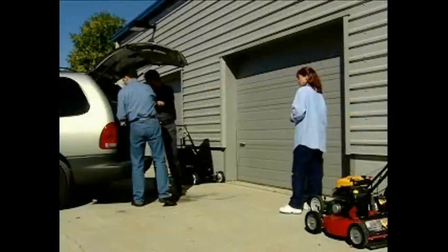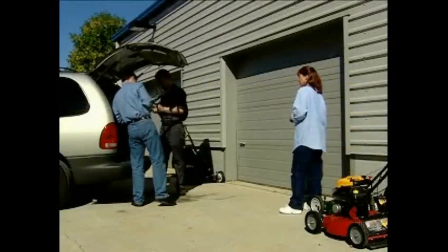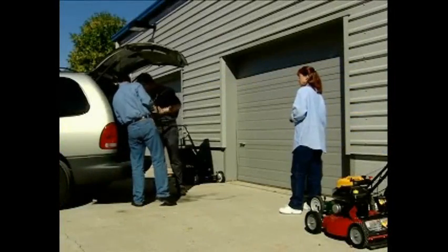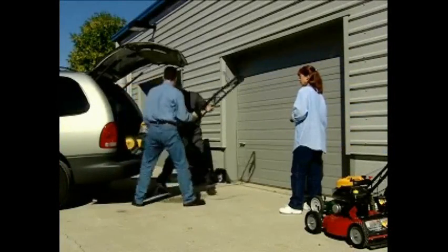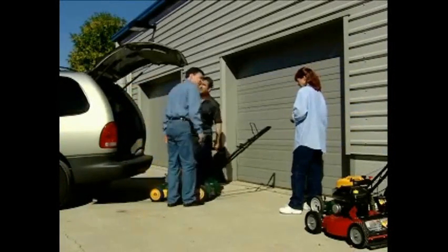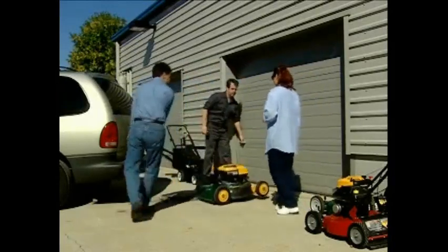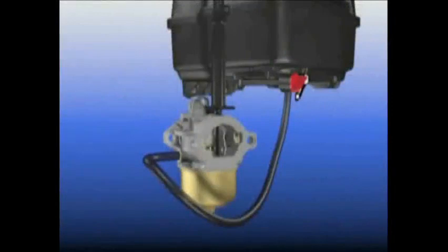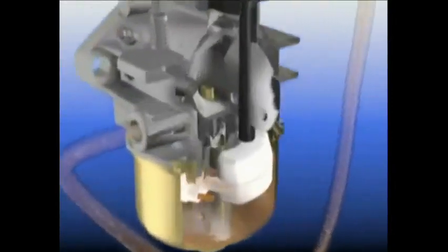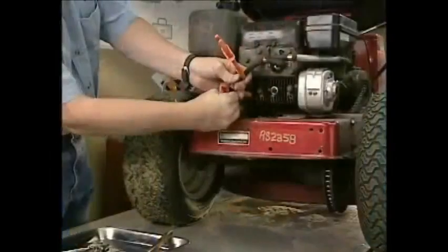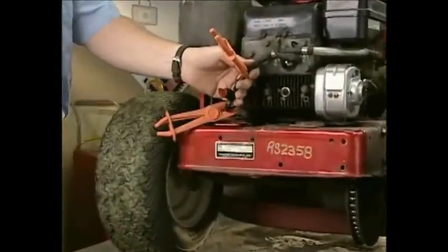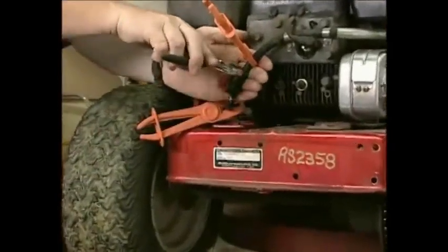One additional condition that can occur while the engine is not running is float bounce. This occurs when the equipment is transported on a trailer or in the back of a car or truck. If the fuel supply shutoff valve is not turned off, the float can bounce. When the float bounces, it opens the needle and seat, allowing unwanted fuel into the carburetor bowl. When enough fuel overfills the bowl, the excess fuel migrates to the crankcase. A quick and easy fix is to install a Briggs & Stratton fuel shutoff valve in line between the fuel